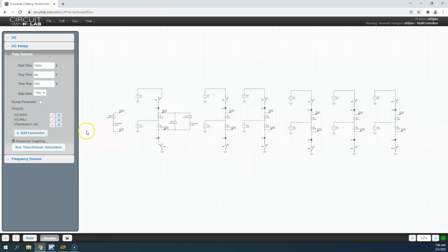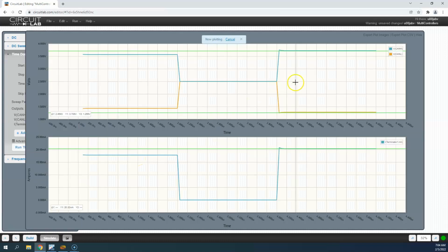I'll go ahead and run the simulation. What we have here is the transmitting controller, where it's transmitting that last bit of the cyclic redundancy check, assuming it's a dominant bit. And then we go to the acknowledge delimiter. This is 2 microseconds where everybody is in the recessive state. Everyone should be in the recessive state during this period of time.